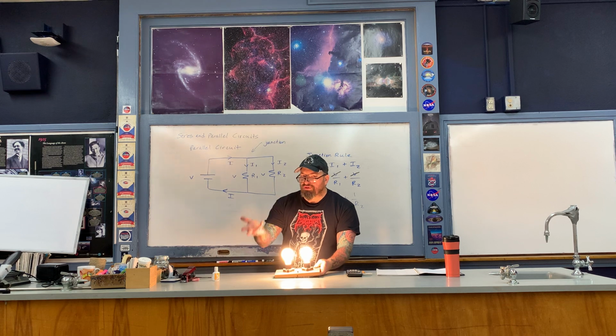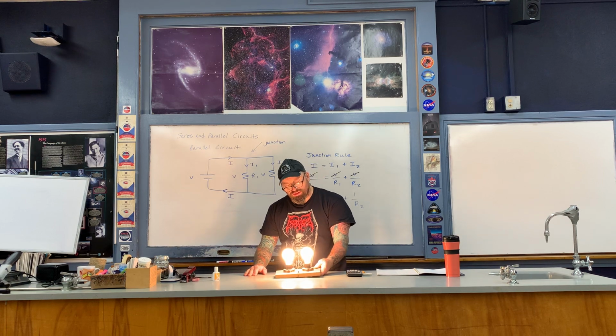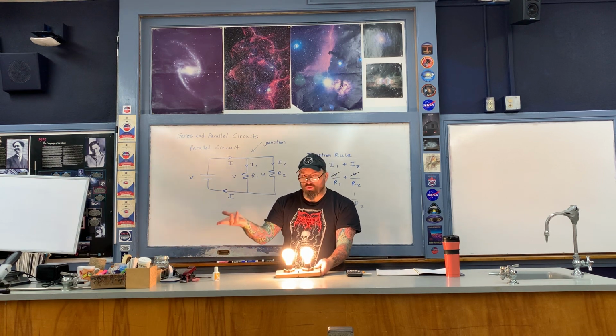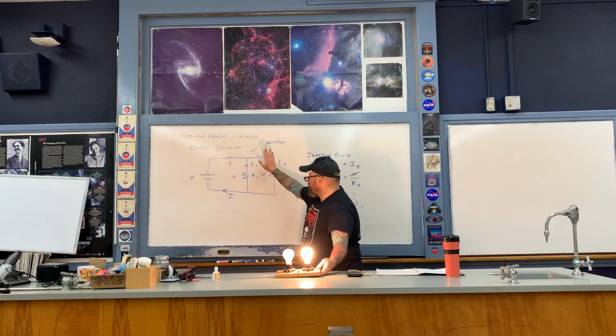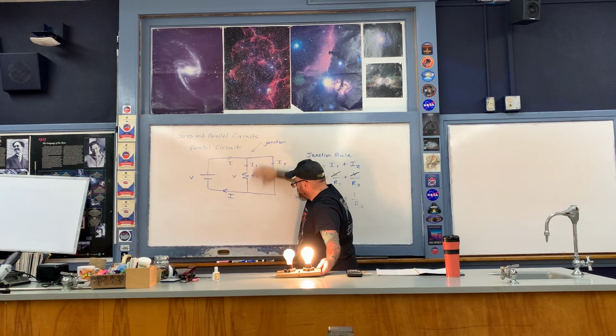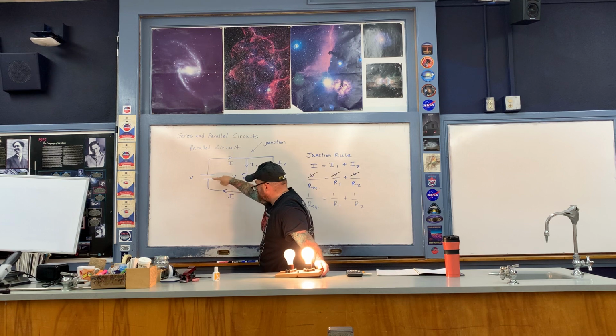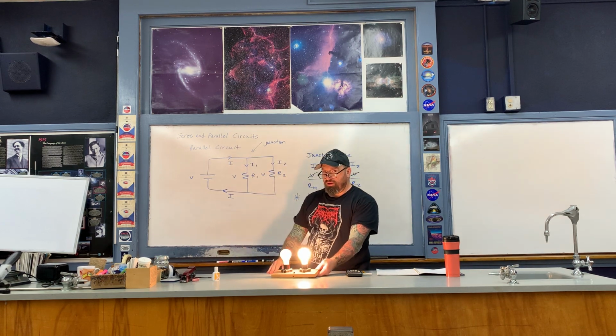Okay, now most of the devices that you have in your home are hooked up in parallel with respect to each other. There are some obvious advantages in doing this. For example, I could turn one of the things off, like so, and when I do, it's like I opened this portion of the circuit, so there's no longer any current flowing through this. There's only current flowing through this loop here with the single light bulb.